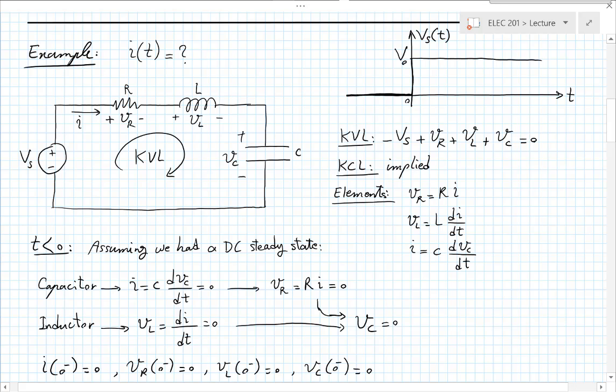Now, if the resistor is really, really large in its resistance, then it will waste so much of that energy that you will not even be able to complete one full oscillation cycle. And that's why you have that critically damped situation and eventually overdamped. So you will not see oscillations anymore. So this is, in a qualitative manner, what happens in the circuit.